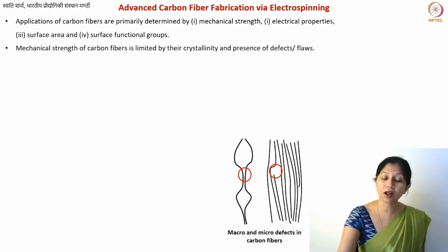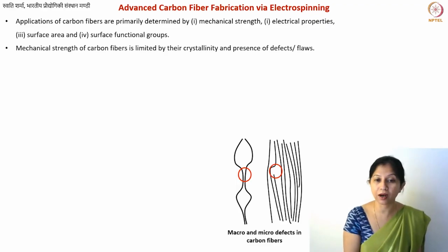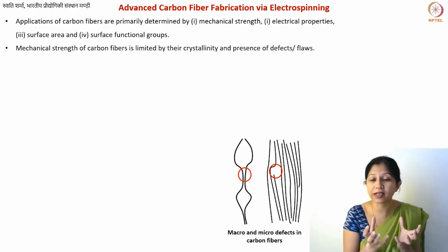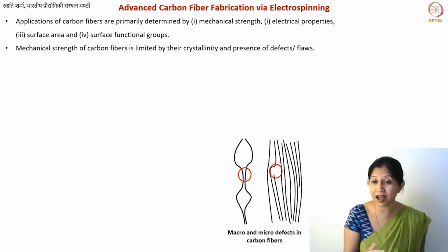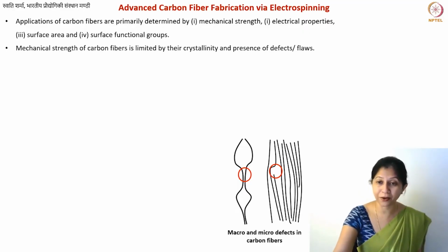Okay, if you look inside a transmission electron microscope at the microstructure of your fibers, you can also have, like I have shown again with a circle, regions where you do not have any graphitic planes. You can call it an amorphous region. You can call it a region with randomly oriented atoms with random bond lengths, but you do not have sp2 type hybridization, or any graphite crystallites.